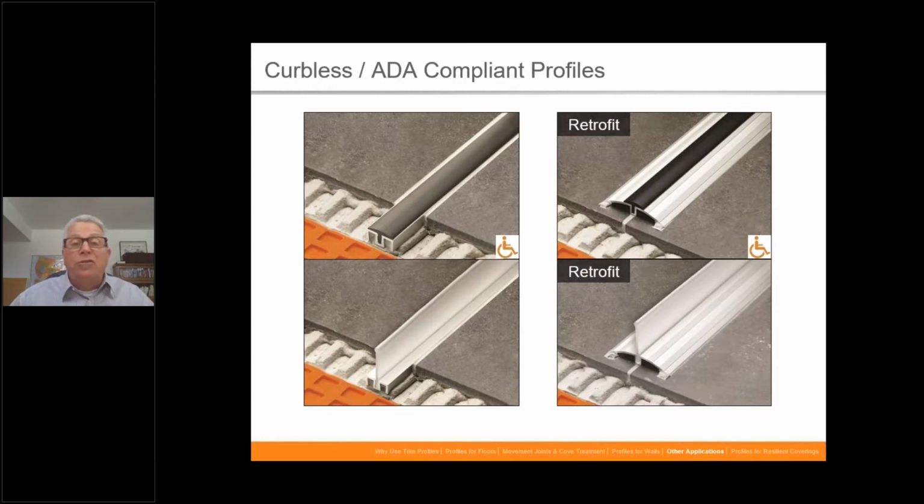Whether it's curbless and you just remove the curb, or whether you're truly building a barrier-free shower, which is a lot more than just taking out the curb, right? There's other aspects to building a barrier-free shower as far as dimension and access, and many things come into play there. But a lot of times, you now have no curb, you have no door. How do you keep the water in the wet area, not coming out onto the floor? There are these type of profiles that are available on the market too.